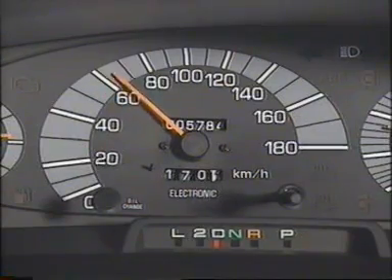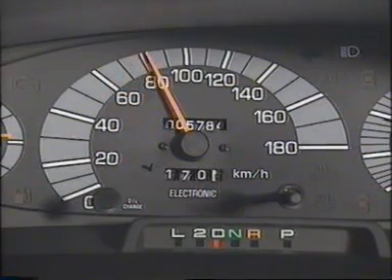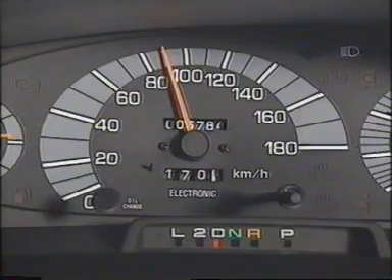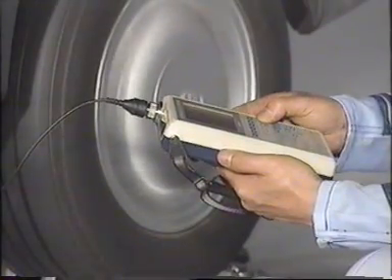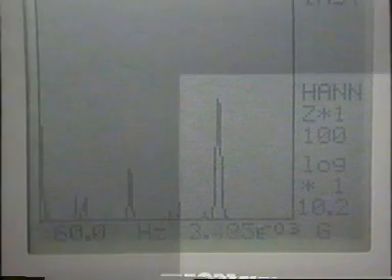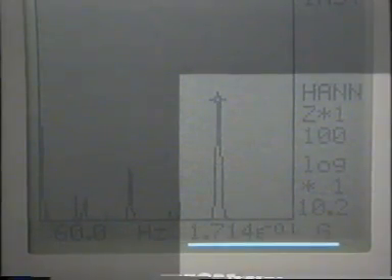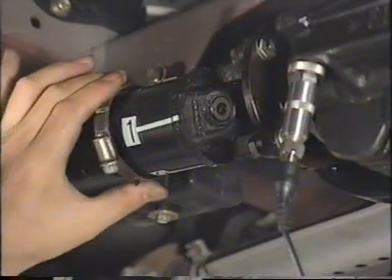When the booming is heard, this person sounds the horn to signal the other person. When the second person hears the horn, he checks the vibration level reading on the frequency analyzer. The reading is 0.17 in this case.